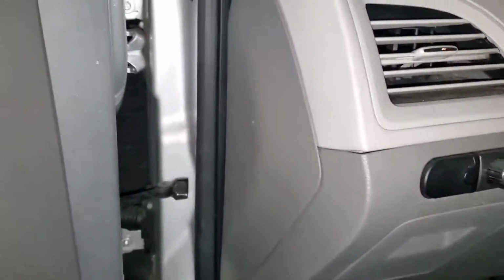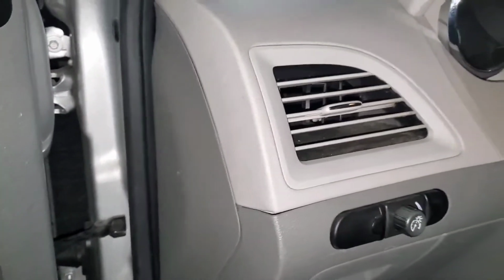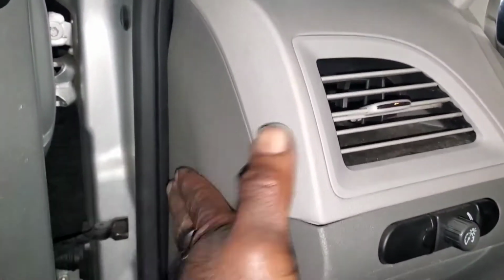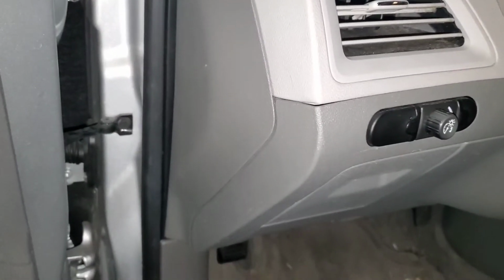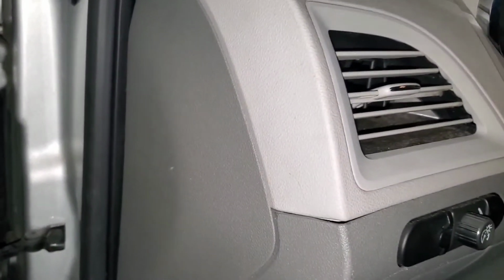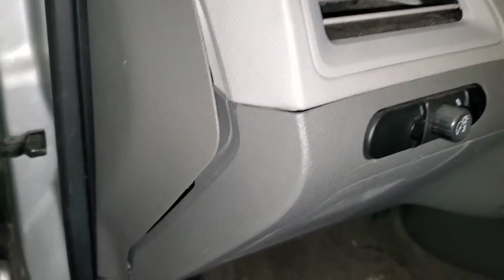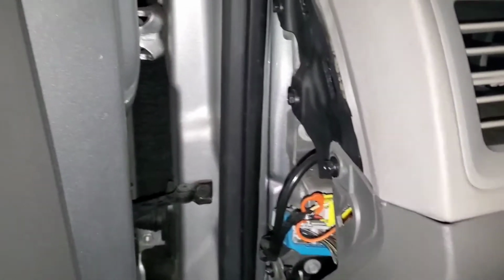All right, first things first, here's the battle plan so everybody can follow along. This trim panel on the side pops out. So does this trim panel down here. So let's delicately do those two now. Little pry tool here. Do this one. And you can see the retainers pop out easily. Put that in the passenger seat.